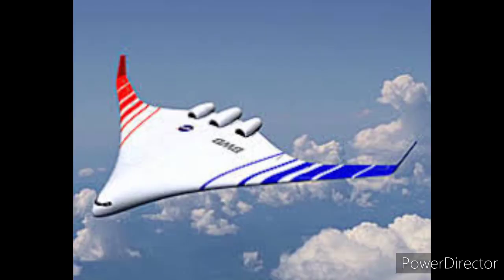So with this I covered two types of wing. One is delta type and the other one is swept wing. We have rectangular design, elliptical design. Elliptical design is not shown in the figure. Elliptical designs have the advantage of less drag and more lift according to the pressure profile. But again, that is only used in the military segment mostly. It has certain disadvantages when flying at subsonic cruising altitude.